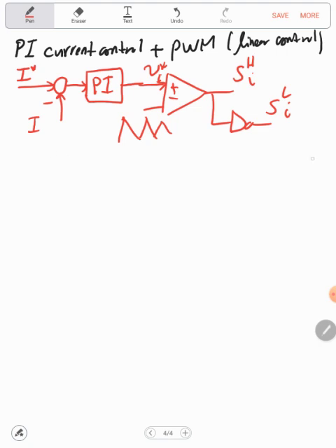However, in the vector control we cannot use the IA, IB, IC reference currents in the machine variable, because they are alternating, and simply the PI control will suffer from the tracking accuracy. So the best is to use the PI control in the QD reference frame.